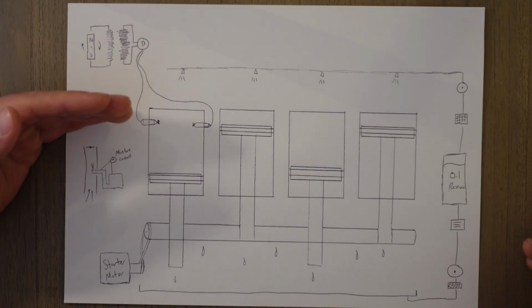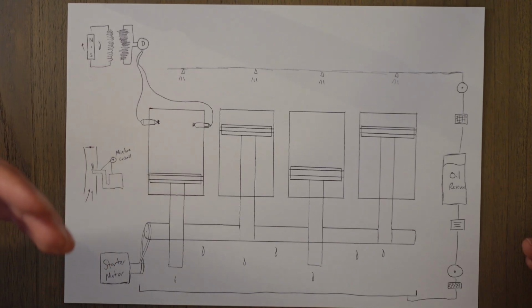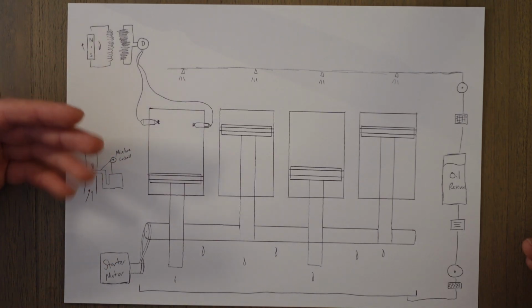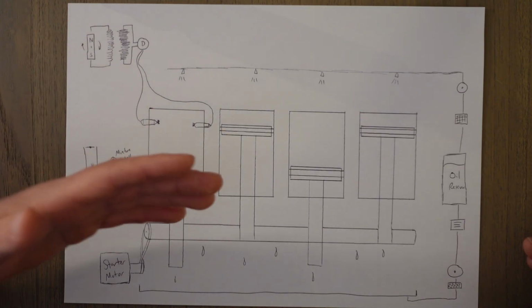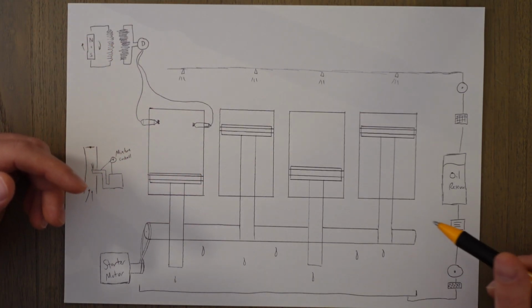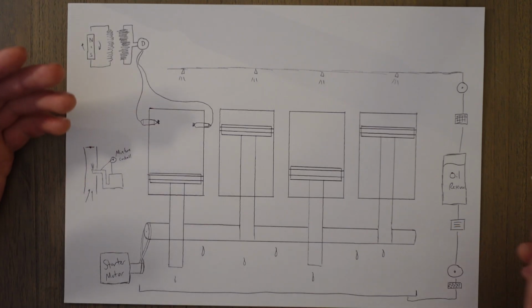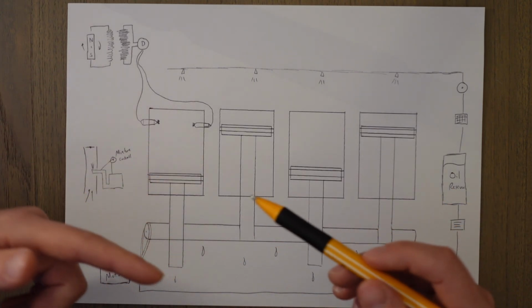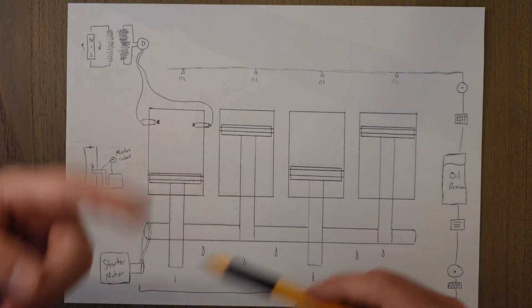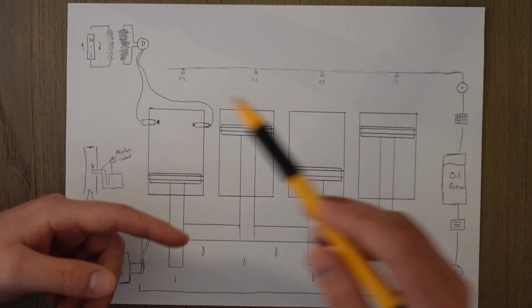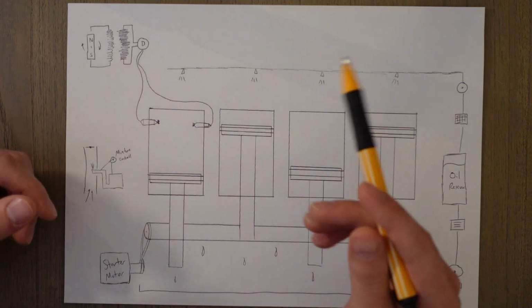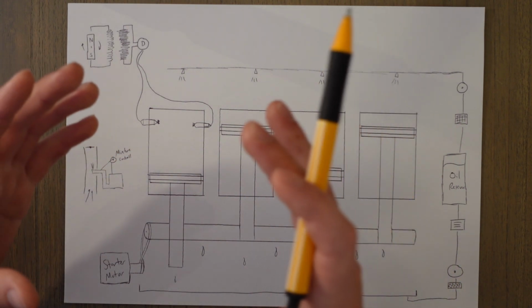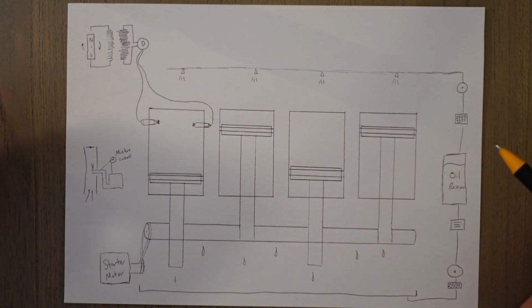And a supercharger is normally used to do this, and it is controlled via gears or something from the engine. Or you can get a turbocharger, which runs off the exhaust gases flowing over it like a water mill or something. It turns the turbocharger, which is connected to an impeller at the front, which sucks up air, just air in a turbocharger, and compresses it before you add fuel.